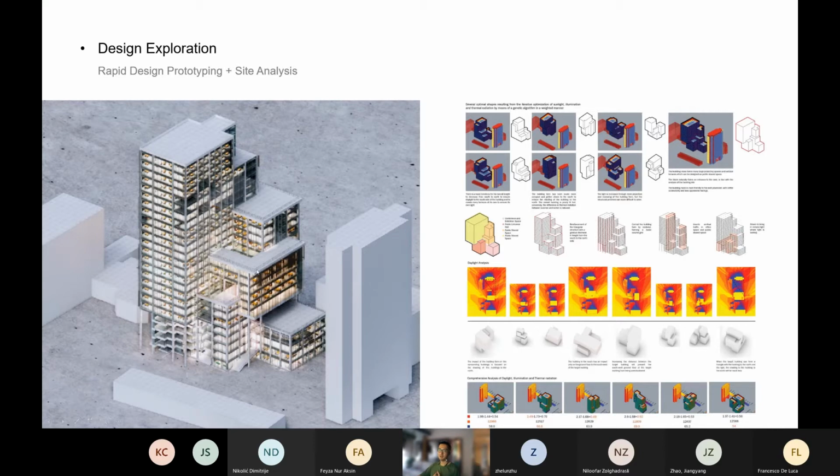But the other smaller boxes on the block of the building will all be hiding in the shadow cast by this large building block. And if you have some experience in passive design, you may be familiar with a strategy called the solar envelope.